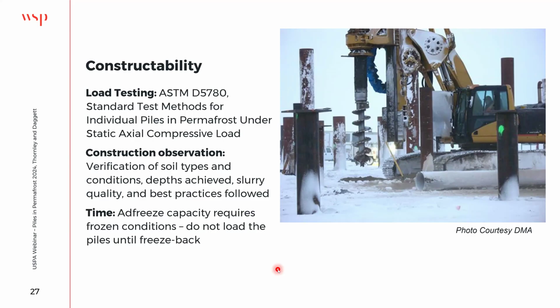Construction observation, just as with every other part of the construction process, it's important to verify that you have the soil types and conditions that you thought you had when you were in the design process. And so providing that construction observation during the construction, looking at depths of the piles, did they actually get down to where we needed to go?